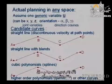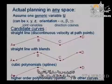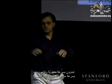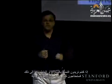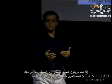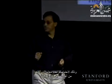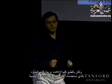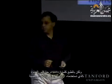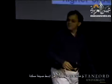Say you're starting from a certain position, ending at a certain position, starting with velocity 0, ending with some velocity, that's about it. If you want to control acceleration, deceleration, things like that, you need a higher degree polynomial because you need more coefficients to satisfy that motion. We'll see that in more detail. But of course, the higher degree polynomials you use, the more complicated the formulas get. Usually we try to get away with the simplest thing we can. Okay, so far?